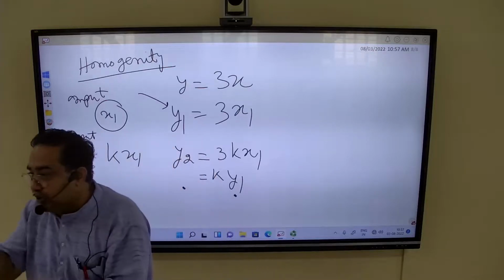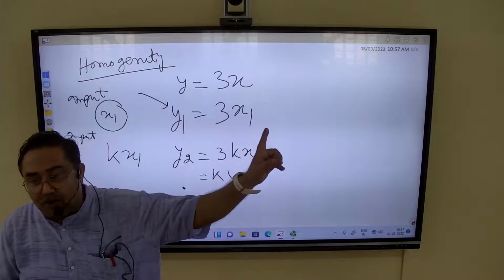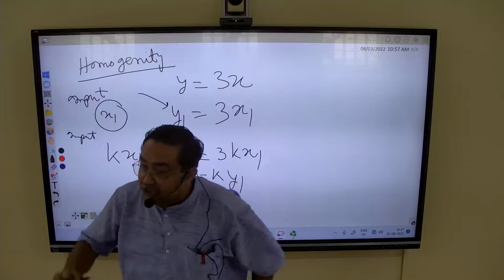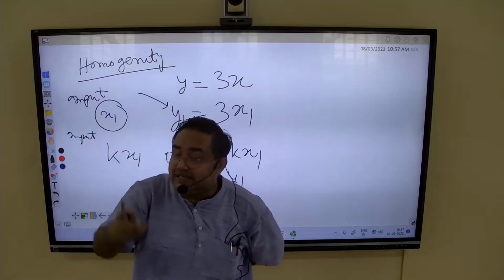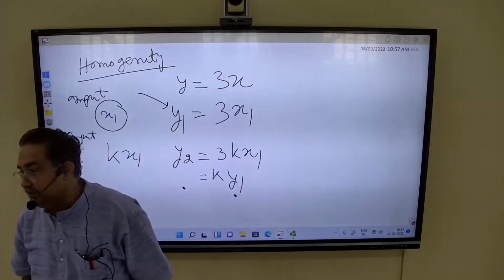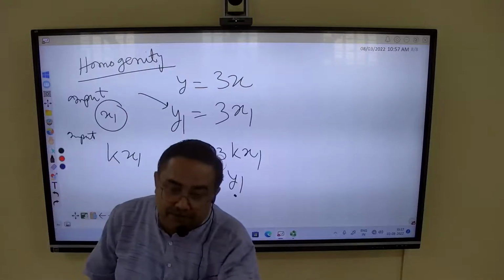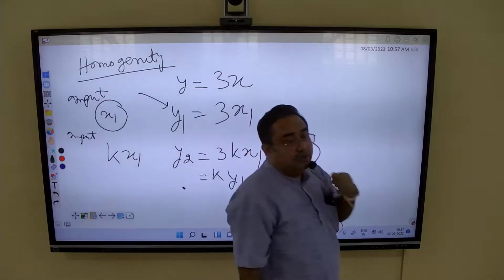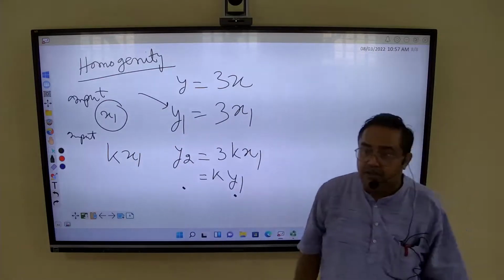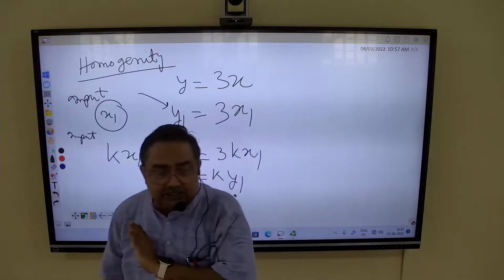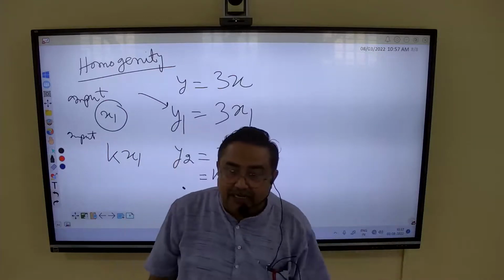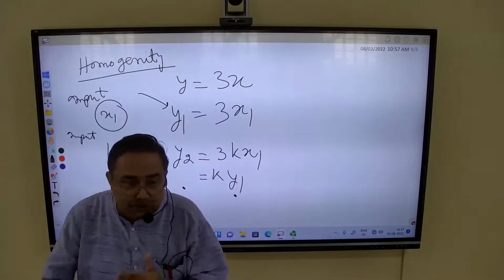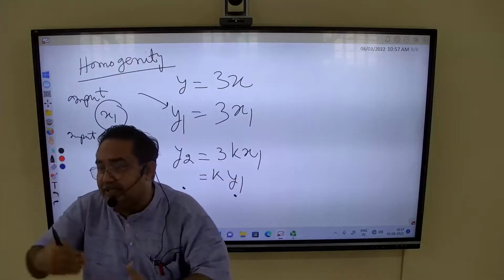And now you also have the reading for homogeneity, because previously you have taken 50 volt and now the second reading is on 100 volt, that is 2 times. Okay, so whether your speed has increased 2 times or not, if it has, it is obeying the principle of homogeneity. But mind it, I have just given you 2 readings. While doing the experiment, verification is not justified by 2 or 3 readings. At least you should have 10 readings. Okay, and there should be conformity between all the readings.